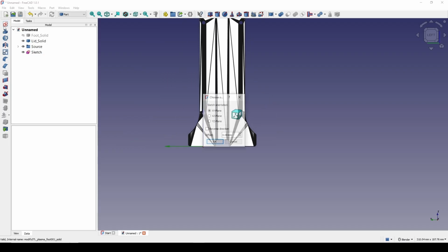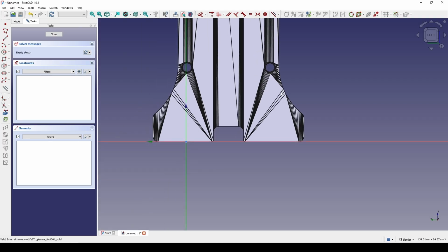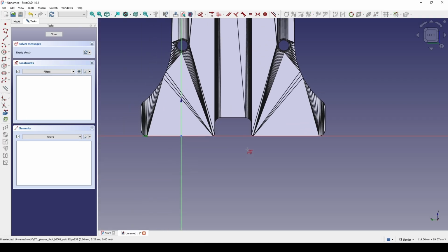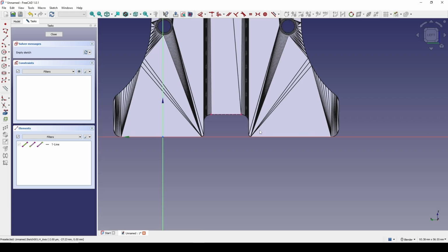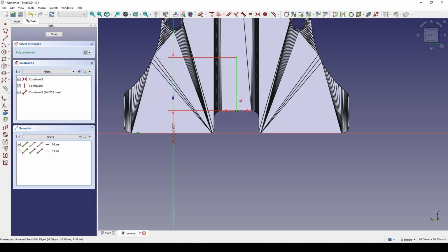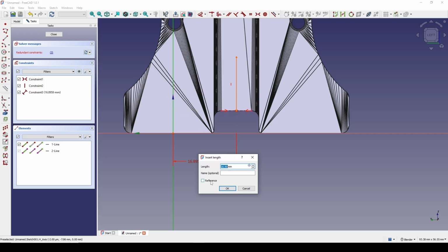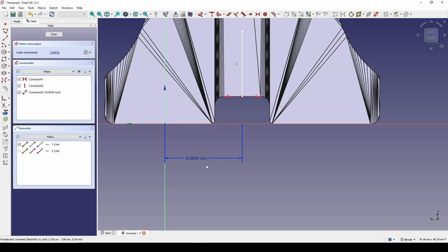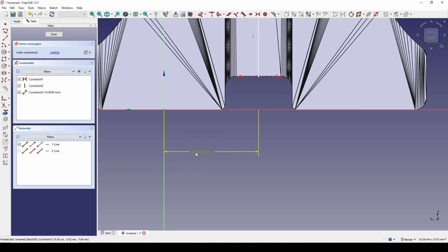So I create a sketch in the left view. So go to the right view and click on the reverse direction for the left view. Click OK. From there, I will reference this line. I create a line and move somewhere in the middle to see the symmetry constraint appear, and move this one up. And I select this line and I hit D, and I click on this line, and I have this number. I click on the reference, and you remember these numbers.